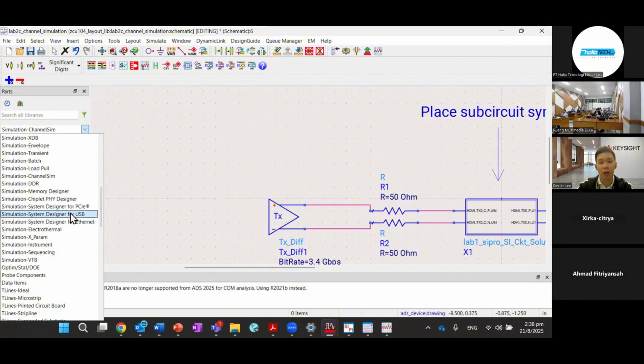We have a lot of standard driven workflows whereby you can run these features with a compliance test that's the same as our Keysight instruments, and then you can get a report of whether your design meets the compliance. For example, for PCIe, we are supporting up to PCIe Gen 7 for this release. We'll look at memory designer later.